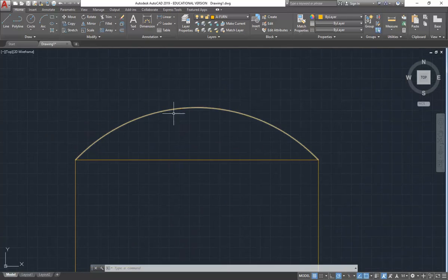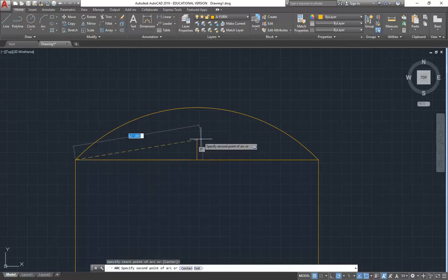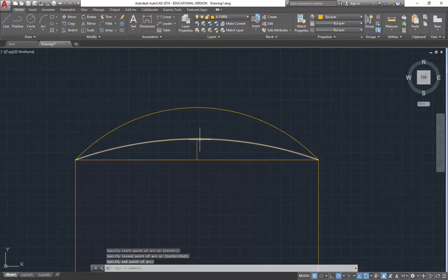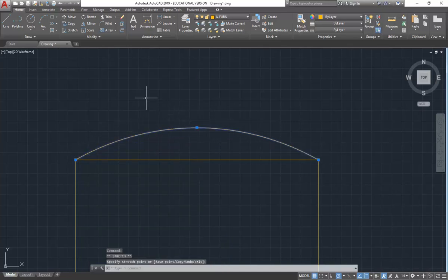Well, kind of. If you wanted that, probably at first, the method I showed you with the midpoint would work. You could type 100 there. That would work. But what a lot of people would do is draw in an extra line. There's nothing wrong with that. Just like when you're drawing by hand, draw construction lines. So I draw a line from that midpoint, take it up 100. And then when you're drawing the arc, it's really easy because you can just snap onto those points and it's simple and you know it's exactly 100 and then delete your line. So yeah, super powerful but also quick usually and easy.